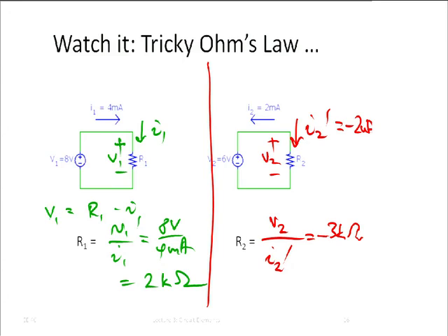Now, it doesn't have a big grandfather's clock inside. But it actually has something that is remarkably similar. It uses a quartz crystal that also moves back and forth, usually a little bit faster, maybe 10 million times a second or so. So a quartz crystal does exactly the same thing. And just like that big grandfather's clock, you can kick it, and it will start moving. And then it will maybe move for a tenth of a second or so, and then it will stop. Right? The amplitude will get smaller and smaller, and ultimately it stops.